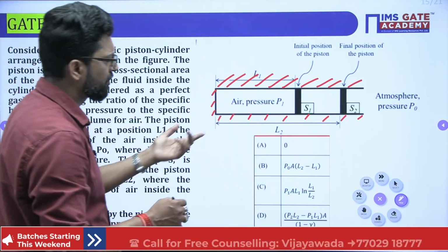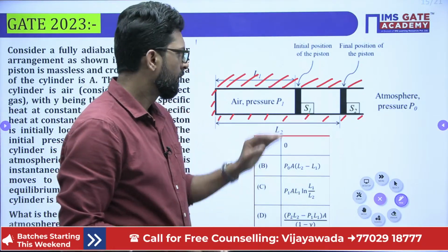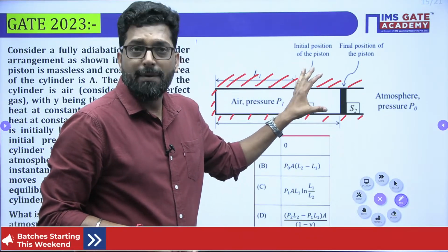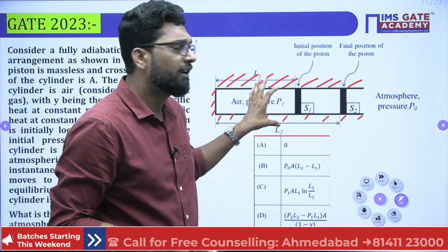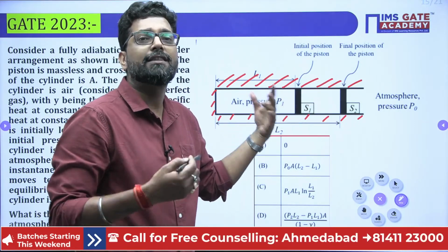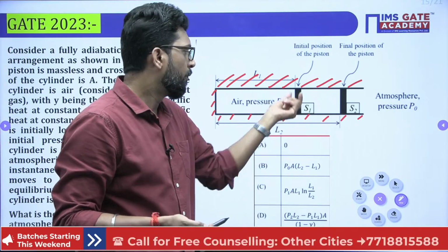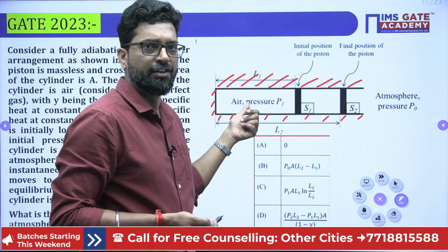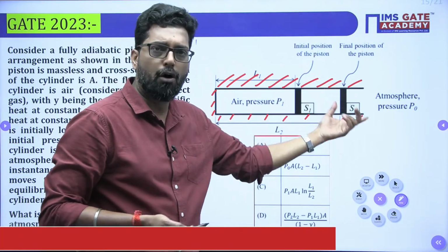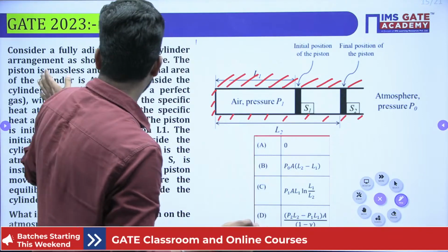In general, the piston is massless and frictionless. See, my dear, if it is not massless, in a horizontal position it is not necessary to consider it, because the weight has no effect in the perpendicular direction. The perpendicular component is 0, so whether it has mass or not makes no difference. Why?